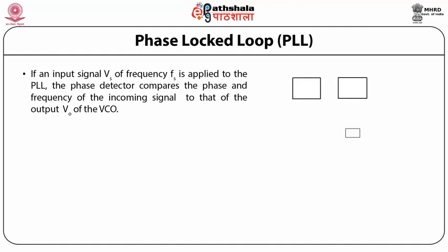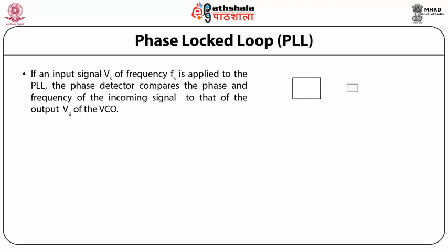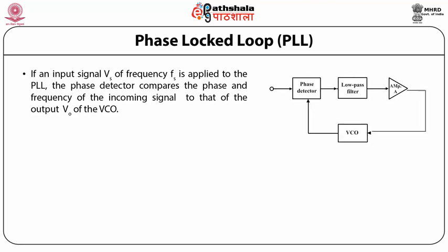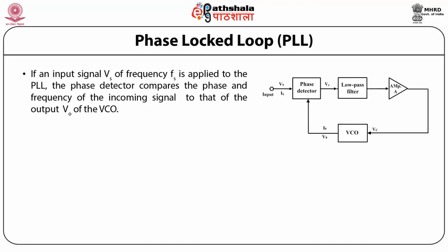If an input signal Vs of frequency Fs is applied to the PLL, the phase detector compares the phase and the frequency of the incoming signal to that of the output VO of the VCO.